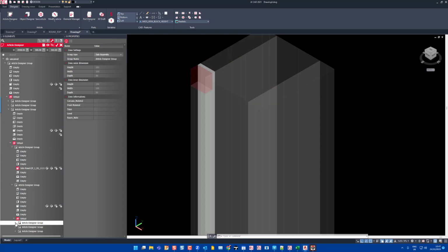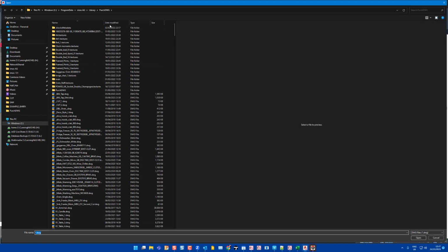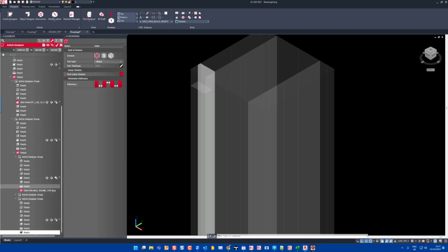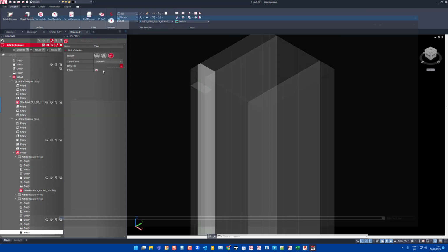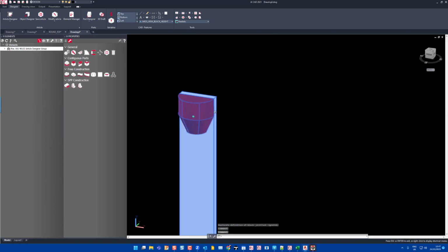What I want to do now is go to my zone at the top here and put in my purchased element. So I'll say that this is a DWG file, and in here, the date modified, I should have half round top, which I want to be in this zone, and then in the bottom I want that to also be a zone with DWG half round bottom. Now currently this is saying extend, and if I was to put the visualization up and just click tick, you can see what that's done is it's sort of stretched that down, and that's not really what I wanted to do.